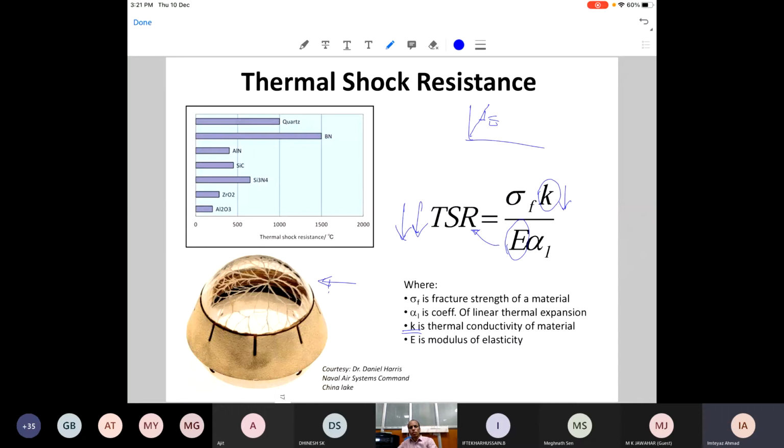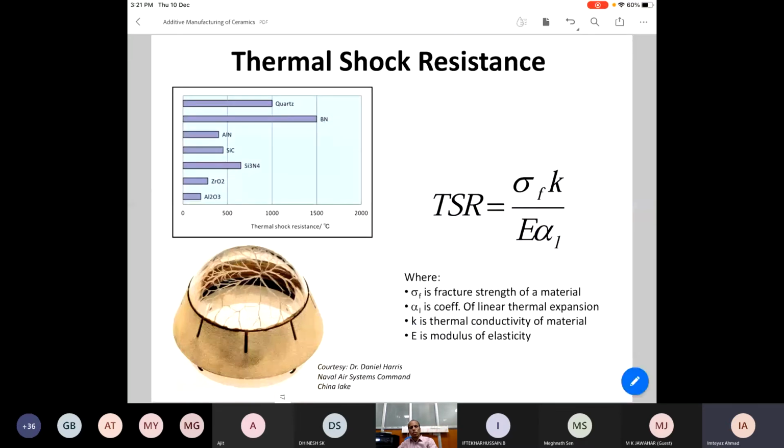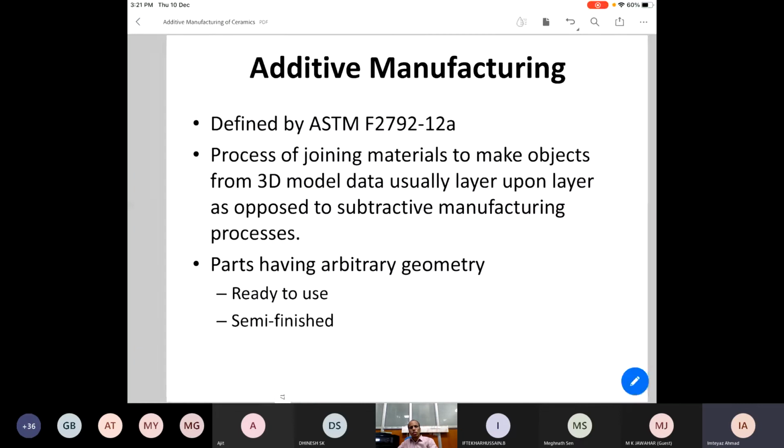When it cools down, when it comes down and suddenly lands back on the airstrip, it cracks. That's a very big problem with sapphire or MgO-alumina kind of windows. So people are looking at whether these windows can be toughened or not. That's the question. So these are the issues.